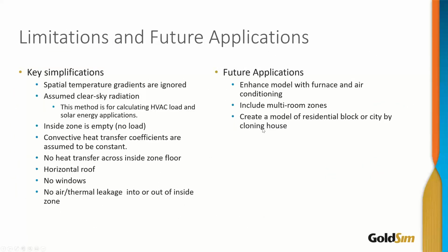So that is some discussion on the solar radiation and some basic limitations. The first limitation, as I stated, is inherent to the transient methodology we use, which is the thermal equivalent network. This network says that each node that we calculate only changes with respect to time, and there's no spatial variation within each node. So that's an inherent limitation.